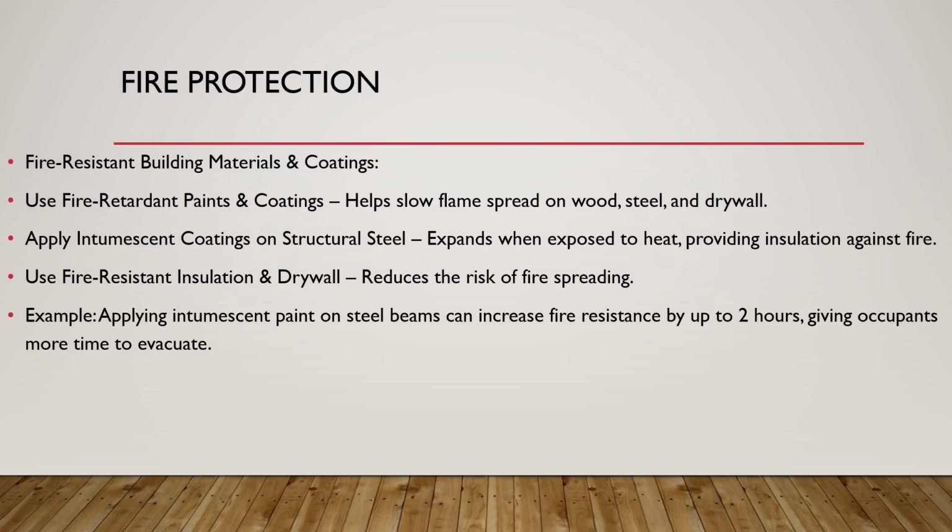Fire resistant building materials and coatings. Use fire retardant paints and coatings. This will help slow flame spread on wood, steel, and drywall. Apply intumescent coatings on steel structures. This will expand when heated and provide insulation against fires.